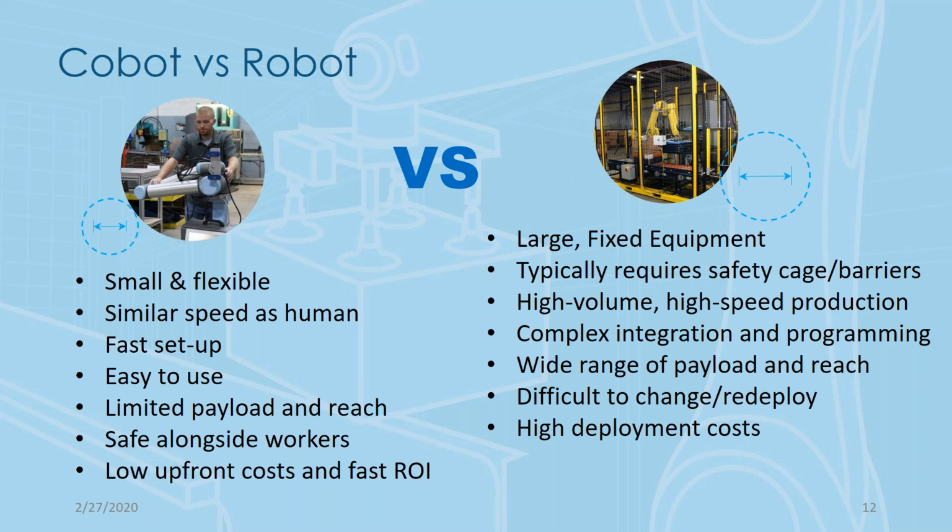Yeah, just a couple of points. Applications where you consider a collaborative robot are typically lower payload, a small light object you're moving around, and lower speeds. Now, if you have a need for a real high-speed robot, that's not going to be a collaborative robot. They're not designed for that. And just by way of illustrating that, with Fanuc's latest family of robots, the design life is 100,000 hours.